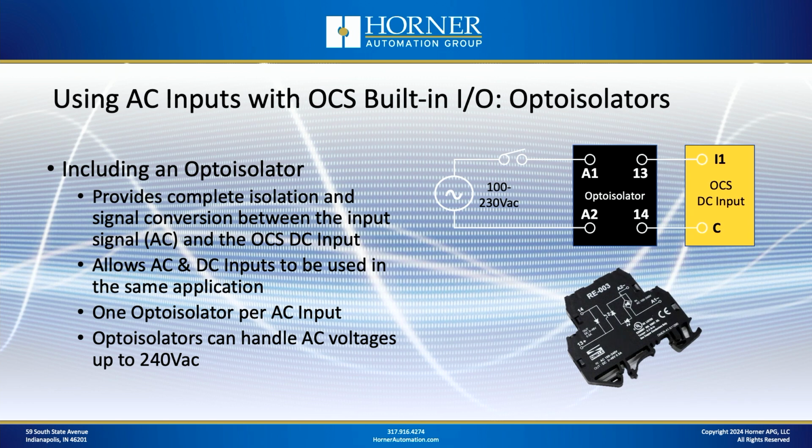You simply use one Optoisolator per AC input, and then you can mix and match between DC input signals and AC input signals, simply putting the Optoisolator in between any AC input and one of the DC input terminals. So they're really convenient components.